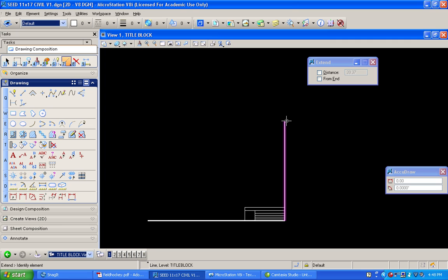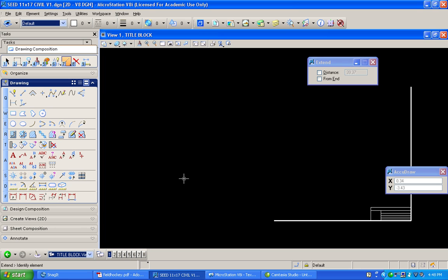looking in my AccuDraw window, and I can just move this. I hit the space bar to switch it from distance angle over to XY coordinates. And it's 11, so we'll just say this is going to be 10. I'm going to shift, hold down my left mouse button and pan, and we're going to extend this line. We know we got 17. Let's assume we can print to 15.75. Okay?